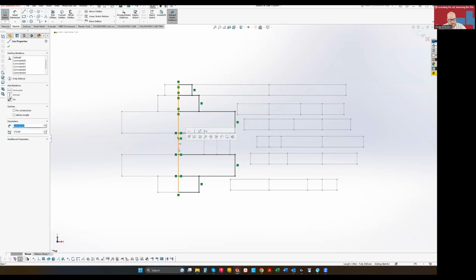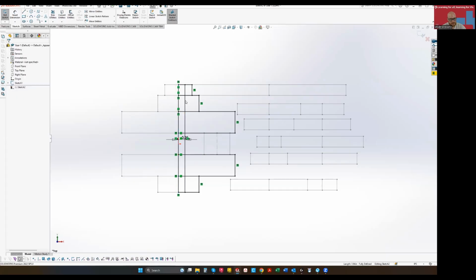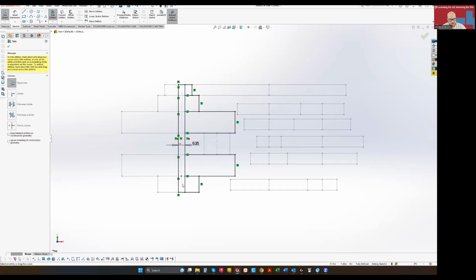Then select that center line, offset, and we're going to make this 0.25. And then, so it's offsetting towards the wrong direction. So let's just click reverse. There we go. And click the green check mark. You can see our dimension line is already in there, showing that it is a 1/4 inch away. And I can trim, and I'm just going to trim out all of this extra down here so that we have a single closed profile as we need, just like that.